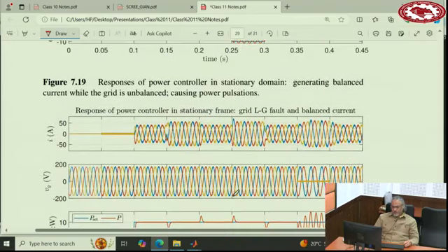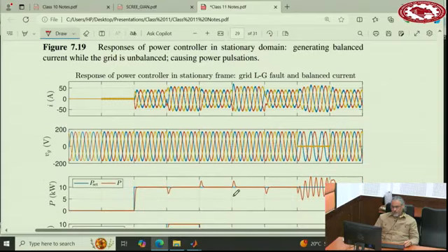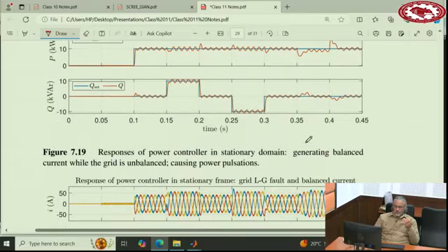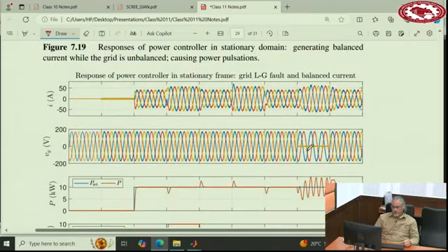This scenario is different, because when I said voltage drops, all three phases drop equally. In a three-phase system, this may not be the case. They have different situations. For instance, maybe one phase drops to 0 and the two other phases do not change. This is a single phase to ground fault. So I check that situation separately.